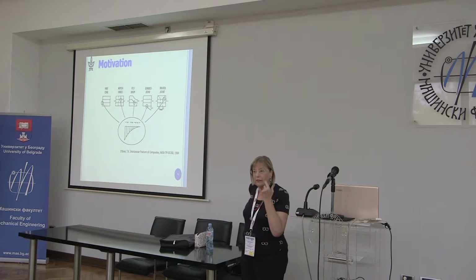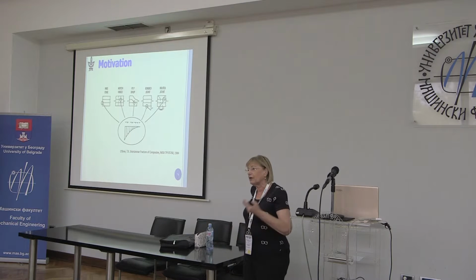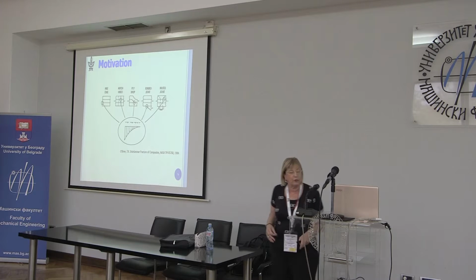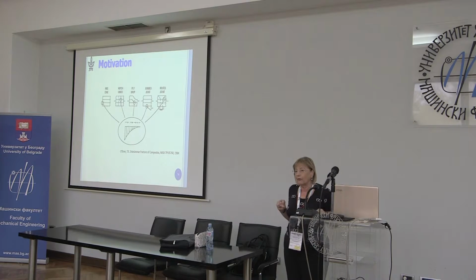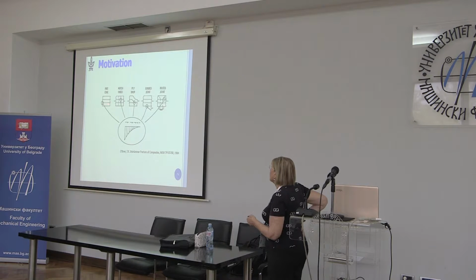Now, of course, there are big databases that the companies and the U.S. Air Force and other air forces have created to do analyses for different types of aluminum, steel, titanium, and so on and so forth. And now we're getting to composite materials, and we have to do similar things. So where are cracks going to occur in a composite? This is a figure for a laminate. So we have an edge effect. You have a singularity, even though there's no crack here, because of this edge effect.